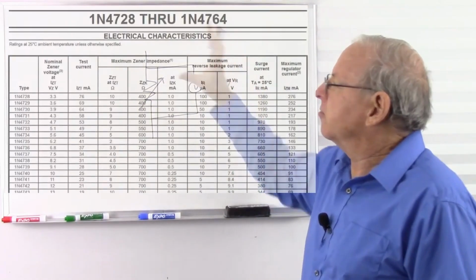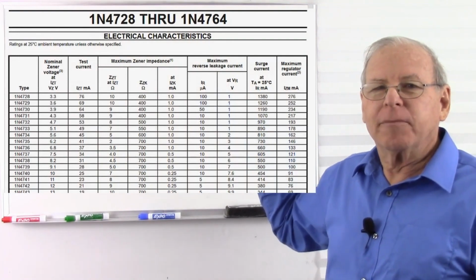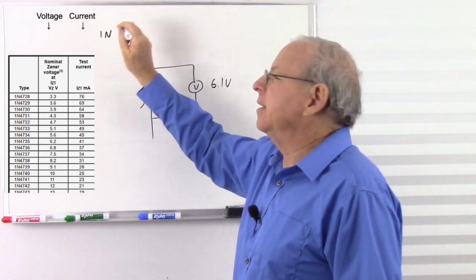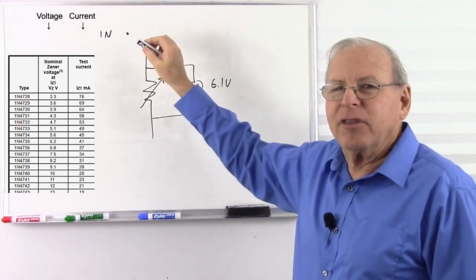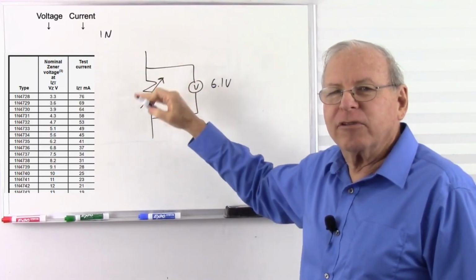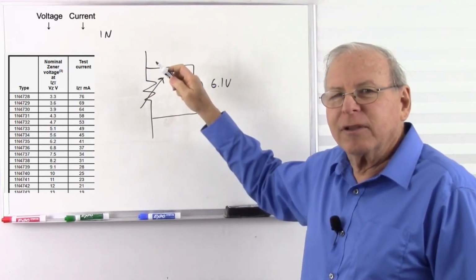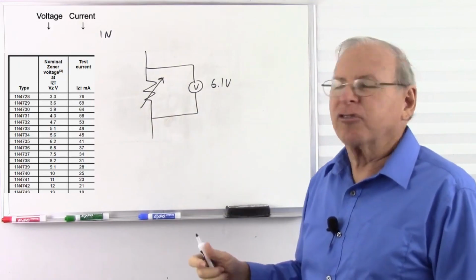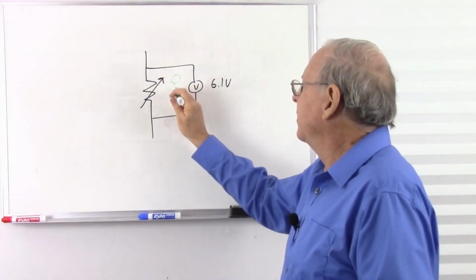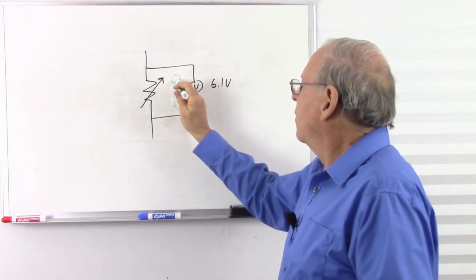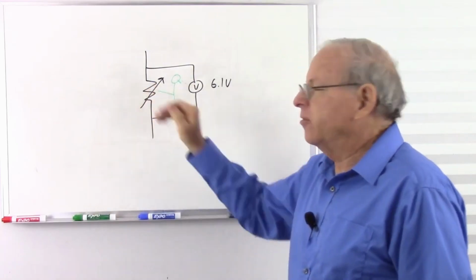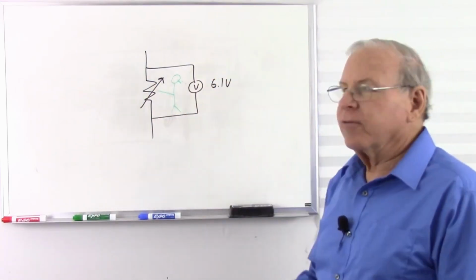And here's a data sheet I'll just throw up here. It's a particular series of Zener diodes, and you see you get a 1N. You see they start with the same two digits, and the other two digits are different. And as we go through the series of digits, we get higher and higher voltages, and just choose the diode that you need. So don't forget we got the little green man in there, watching the voltmeter and controlling that resistor to make that resistance whatever it takes to keep that voltage whatever the rated voltage is.